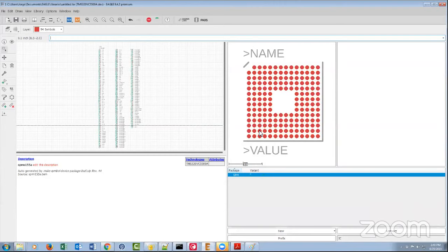Now, usually, this is really neat, but the schematic symbol is fairly large. A lot of times, I've learned some users will actually break the symbol into multiple gates. That way, they could manipulate the component on different sheets. It's just an option that if you want to edit the symbol, you could keep the symbol and then copy paste portions of these pins onto other symbols, break it down, and then create the device again as a multi-gated element.